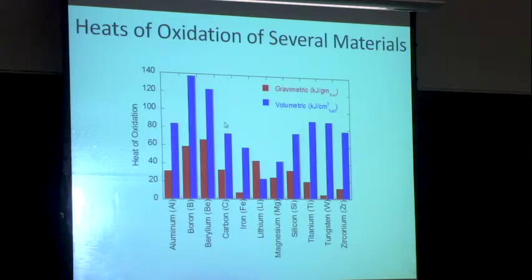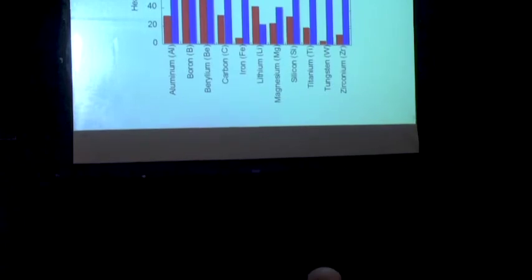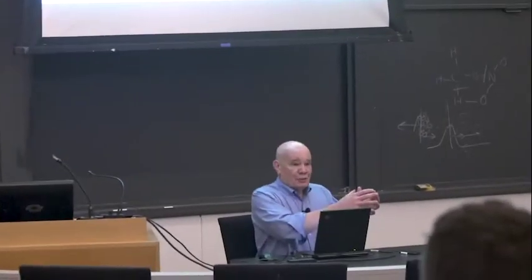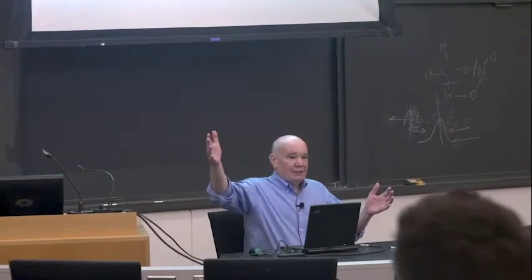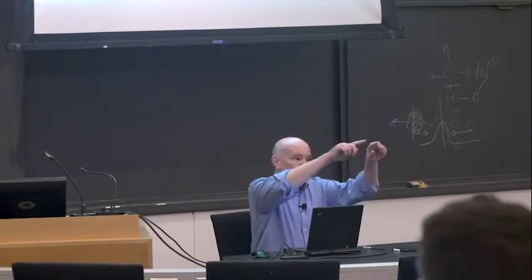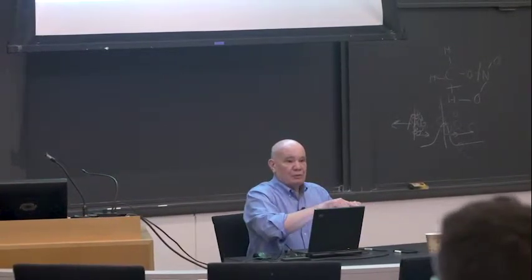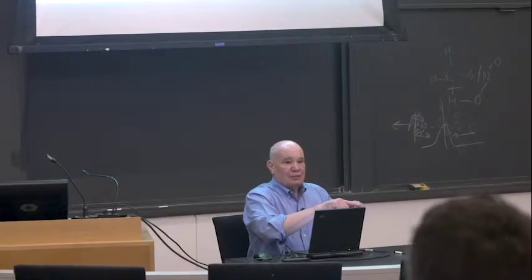So one of the questions that one asks about metal combustion is how do they burn? And they can burn in different ways. If I look at combustion of droplets, like a hydrocarbon droplet, I know in the case of a hydrocarbon droplet, the hydrocarbon vaporizes at the surface and it starts diffusing outward. And if I have air in the ambient, the oxygen starts diffusing in, and I get this envelope flame around the droplet. So I have a vapor phase combustion process.